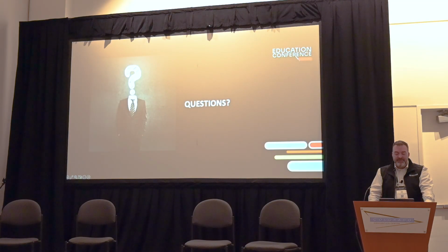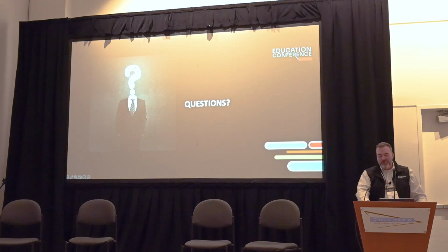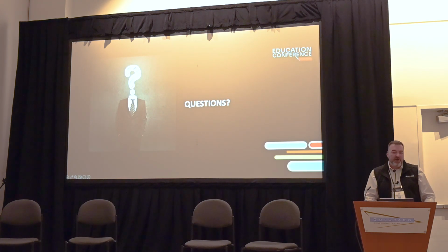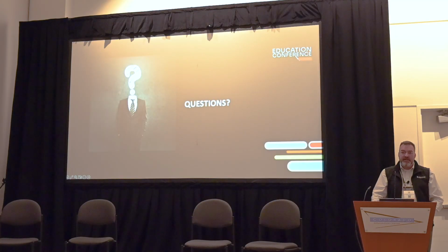Is there a reason for that? Yes, absolutely. There's a very good reason for that. Color lights are a gimmick. If a designer doesn't know how to design with variable colors of white CCT, they probably shouldn't be designing. Color should be used not to bathe everything, especially in a residential property. Good designers know there's enough color present in landscape materials, trees, boulders, shrubs. Use the appropriate CCT. Blend your CCT colors, the colors of white, 2700K to 4000, 5700.